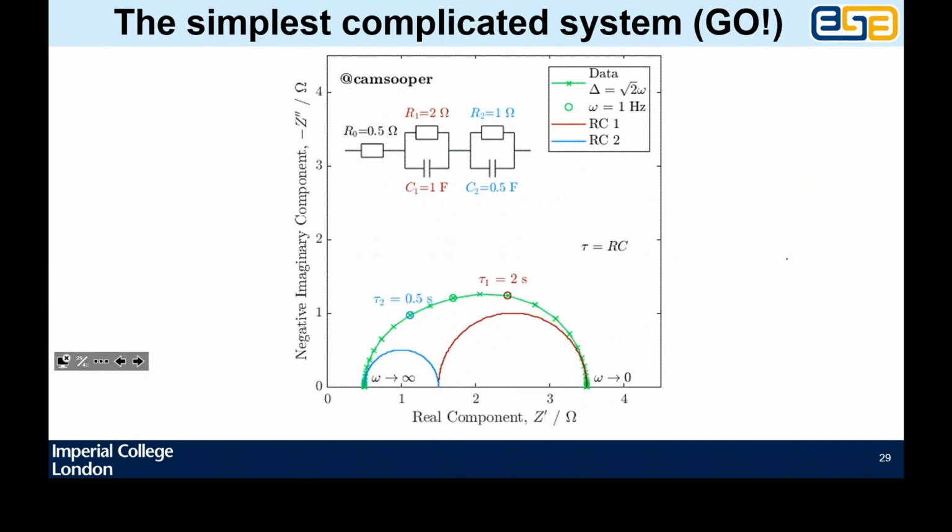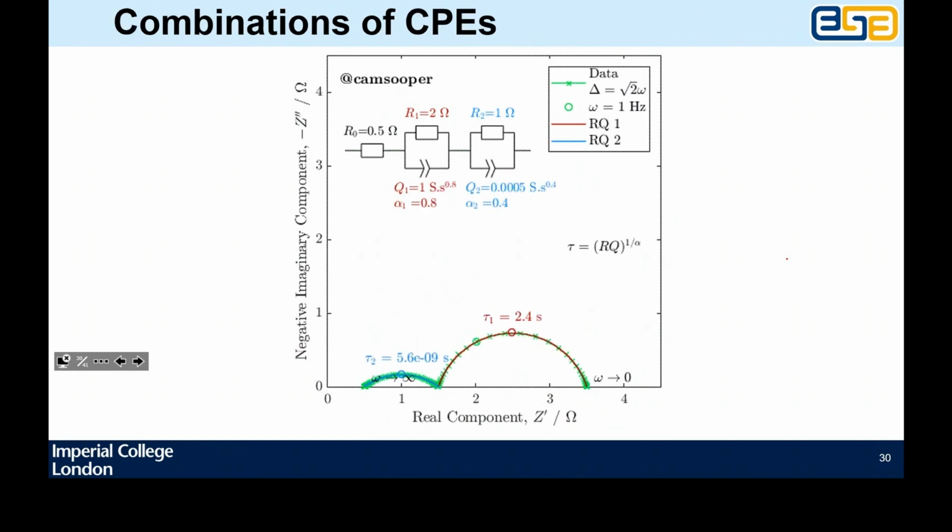But you notice that that green curve, the impedance spectrum that you get from the circuit, has this really interesting thing of going from being two semicircles when the time constants of the two processes are really separate to merging together. And I like to think of a puff of air coming up from underneath the graph and blowing like a sheet, so the green gets blown up until it becomes one big semicircle, and then they swap sides and go down the other side. So the slow process is always going to be on the right, the one with the longer time constant. Okay.